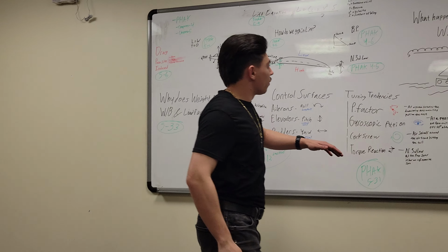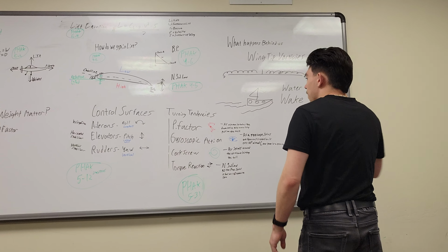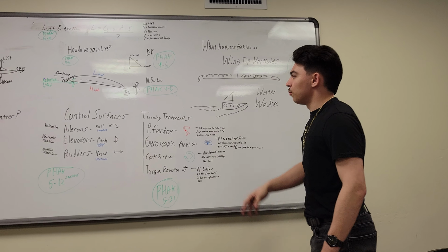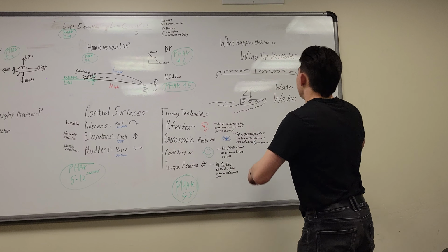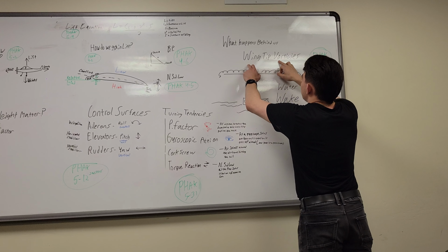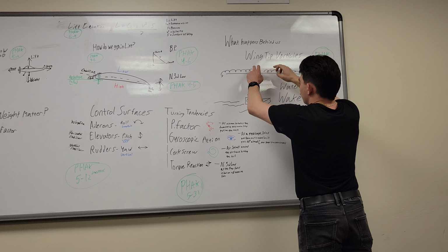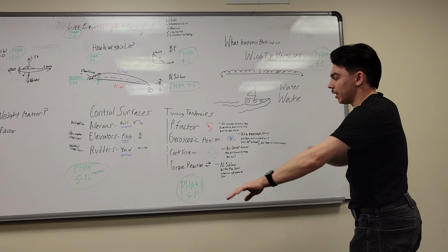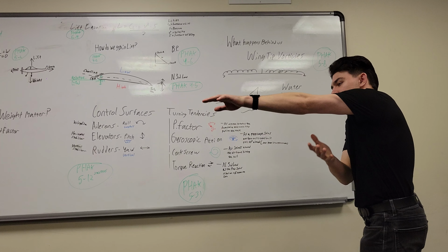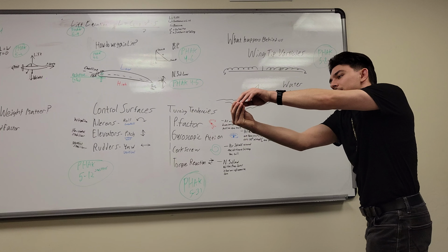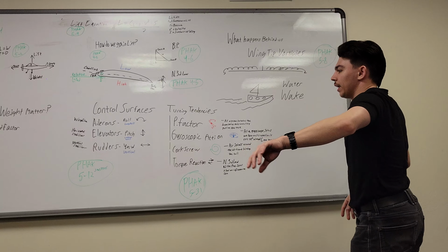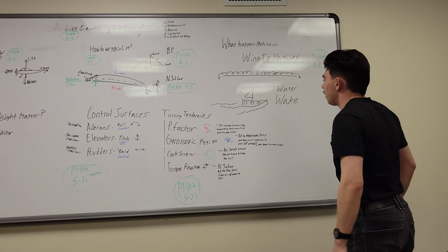Now, let's go over wingtip vortices. So, again, all this wind coming over our wing and all that generated lift, the thrust rotating that wing, all of it's going to cause wingtip vortices. Those wingtip vortices are going to be spiraling off the edges of our wing. And again, as that high pressure meets that low pressure, they're going to be spiraling and meeting at the very tip and going behind us as we continue forward.